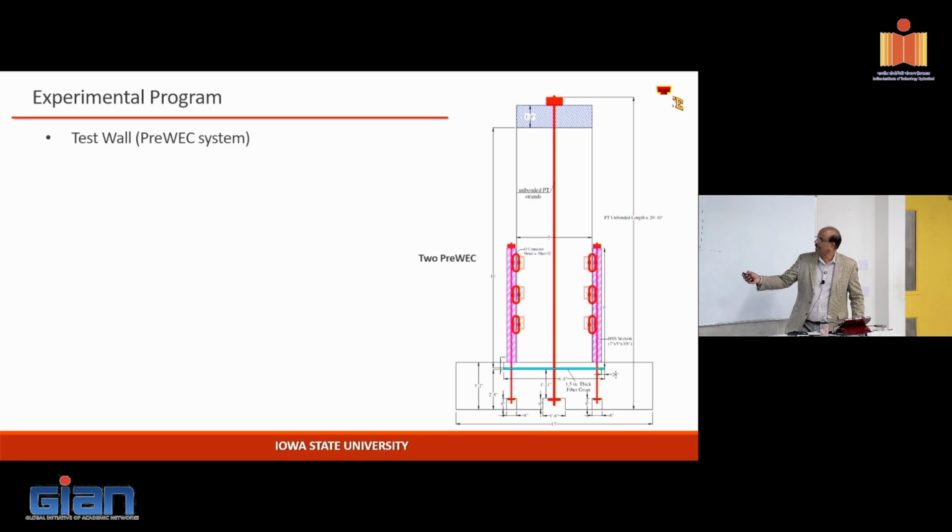So if you lose the strand, basically the wall will come loose, right? So that's why I've been emphasizing the post tensioning anchorage is important. So 2 things we have to do. This is unbonded so that it can survive multiple loads, so you don't want them to go inelastic significantly. So these post tensioning steel are designed in such a way, as I showed you, EQ1, EQ2, EQ3, EQ4, 4 different seismicity levels. Under EQ3, we designed them to remain elastic. If you go beyond, you may allow some inelasticity to come in.